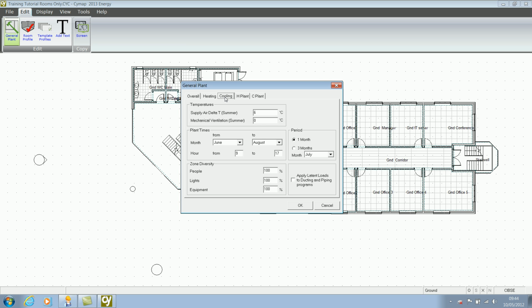Again, this depicts the fact that we're ventilating air into the building untreated. So whatever the peak temperature is in the weather database for the location we've selected, we are effectively ventilating that air into the space untreated. So any fan coil units or air conditioning units applied to the zones or the spaces will be including fresh air in the separate zones.